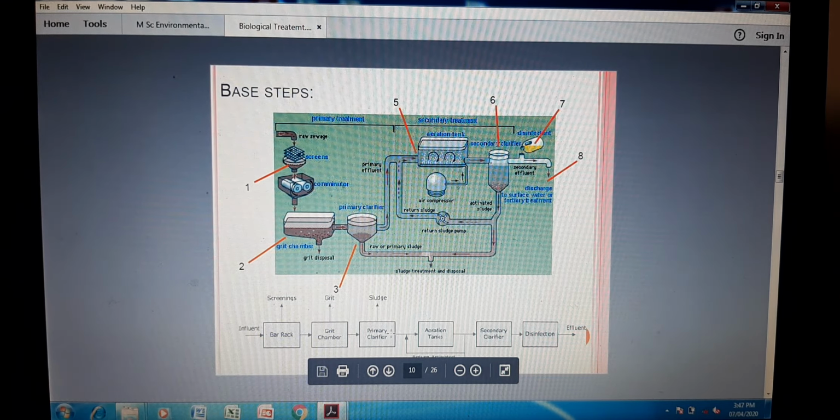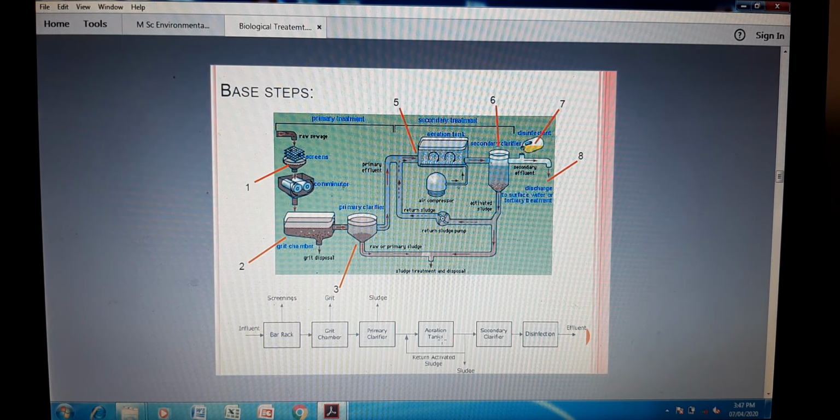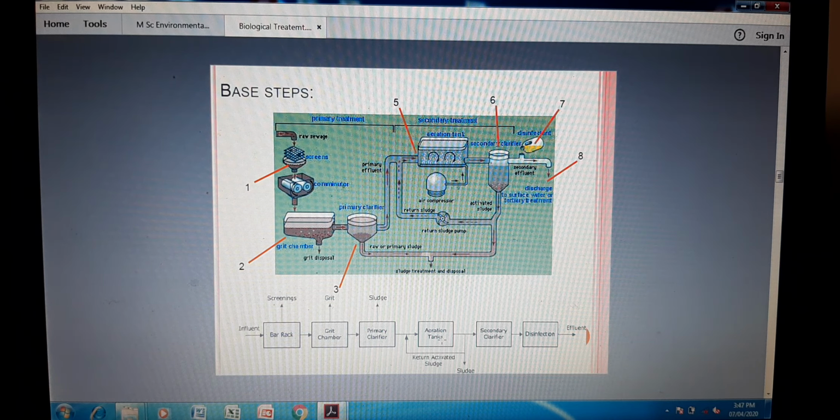But after the primary clarifier, the second is the aeration tank. In the aeration tank, there are some aerobic microorganisms, they are consuming organic matter and converting it into simpler forms, the organic matter which is in the macro forms. When the microorganisms degrade that organic matter into the simpler form, after their degradation, whatever the remaining part is, in the form of dead cells or the sludge, can be removed in the secondary clarifier, so that the water becomes clear, and clear water goes towards the next unit operation, that is the tertiary treatment.